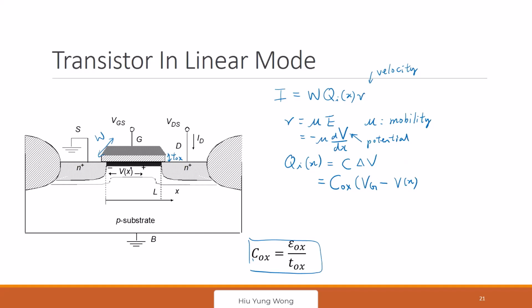But I'm also going to subtract VTH, because before VTH it induces only depletion charge. We don't want to count it because it is not used for the transport. Depletion charge is not mobile. That's why I remove VTH. If I don't subtract VTH, the total charge induced is both the electron and the depletion charge. Is this okay?